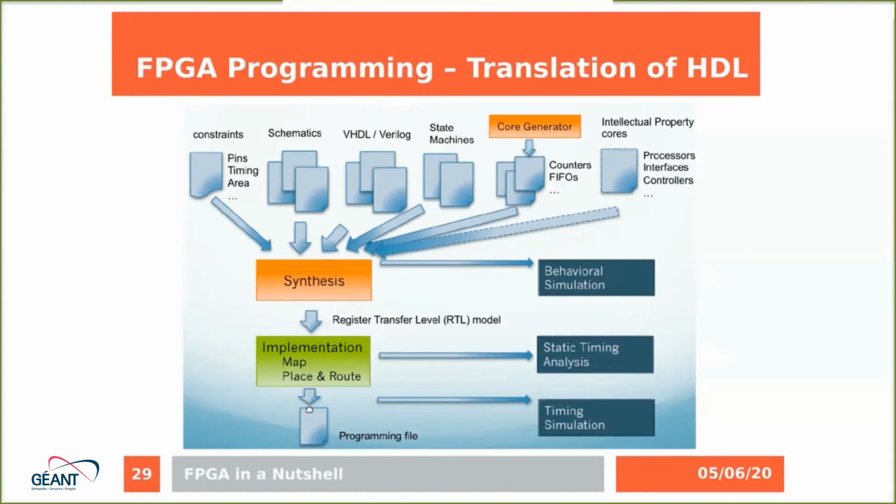Then we start the implementation phase, when we are mapping to the target architecture and we are placing and routing the digital design on the FPGA. In this phase we need to check that the timing constraints were met.